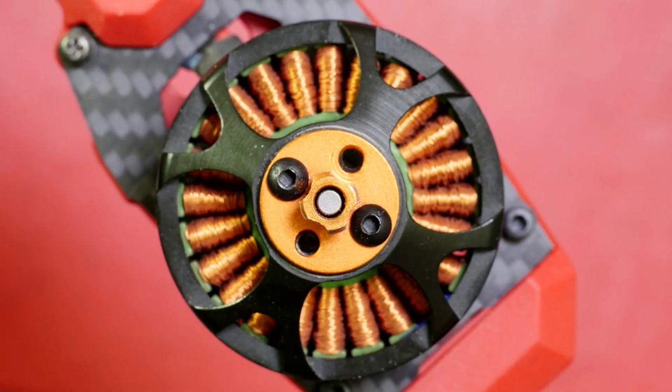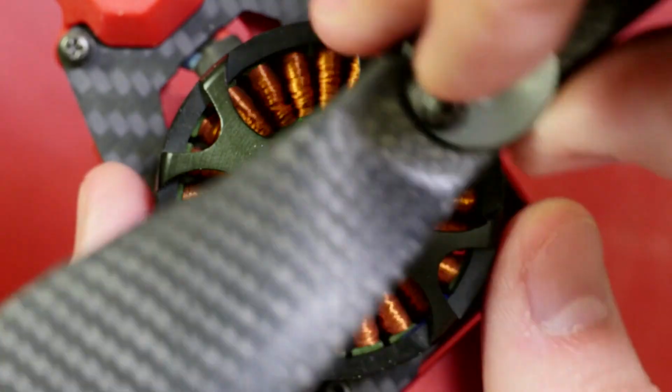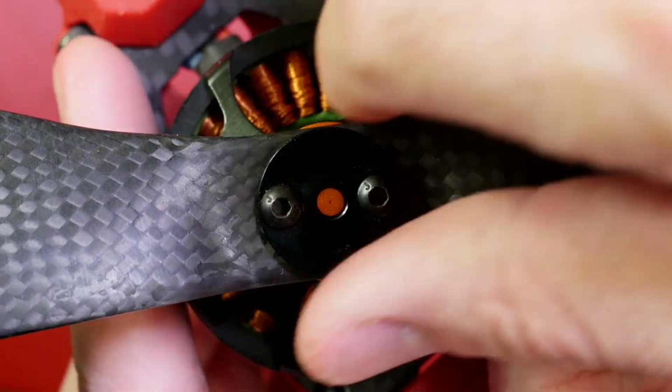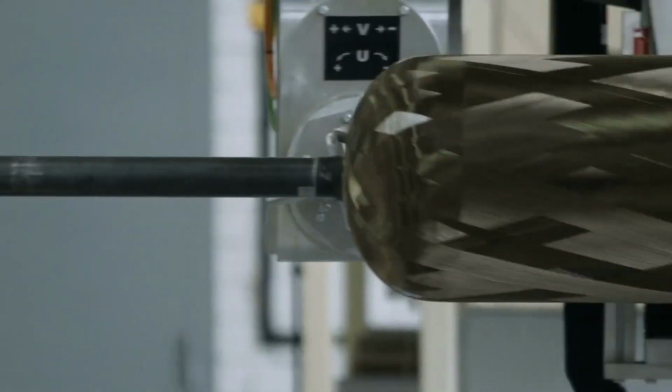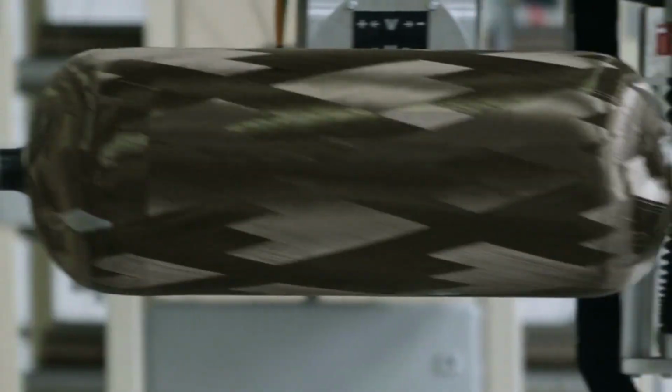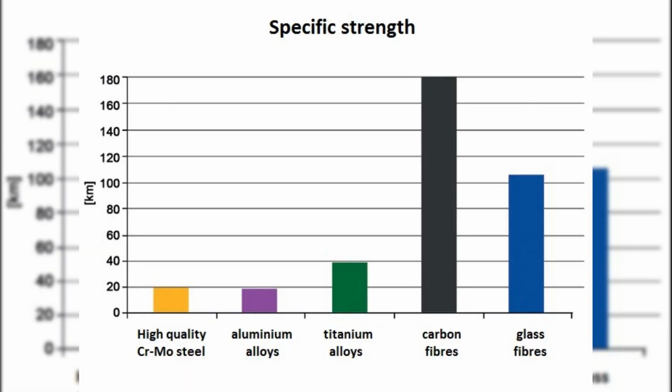One remarkable aspect of this process is that the fibers maintain their shape even under these extreme temperatures. The diameter of the filament remains extremely small, typically around 5 to 7 micrometers. After carbonization, the resulting fibers consist of more than 90 to 95% carbon. This near-pure carbon structure gives the material its exceptional properties: very high tensile strength, extremely high stiffness, and very low weight.